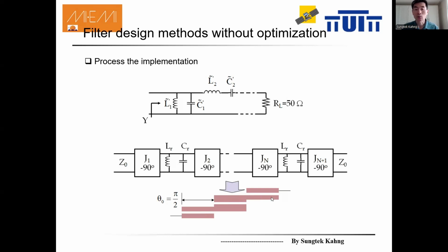Why? For one body, it has two different widths, right? So there's a perturbation. You cannot use just a plain rectangle. That should change like this. Why? Coupling area and non-coupling area for one resonator. The coupling makes the resonator resonate at the desired frequency. They are shifted above and below the target frequency, then you control and change the gap